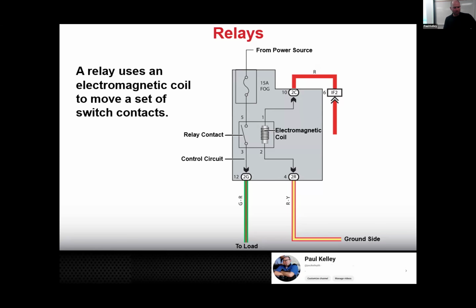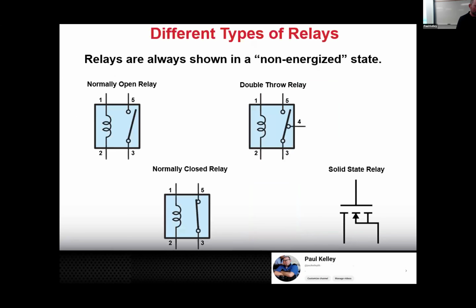If I hear or feel the click, that's this little contactor moving over. Click, click, click. If this is clicking, I could tell a lot about that circuit, and I never even measured one thing. If this is clicking, that tells me terminal 10 is getting 12 volts and terminal 4 is getting ground, because that's what it takes to magnetize it to give me the click, right? So that's why it's helpful to really know the whole theory, the whole thing. You can do quick diagnosis if you understand it.